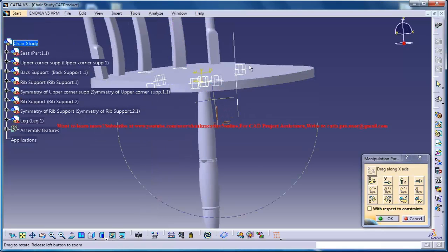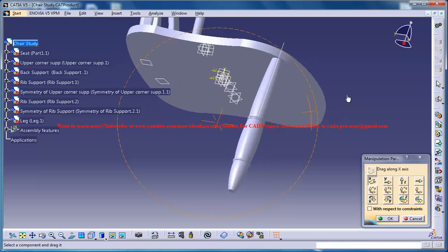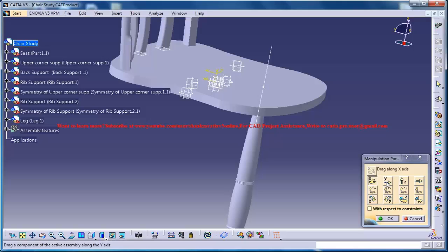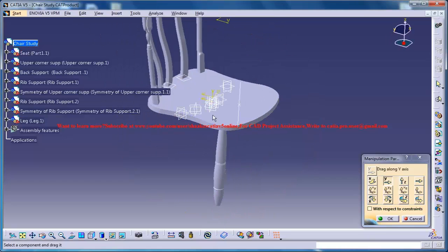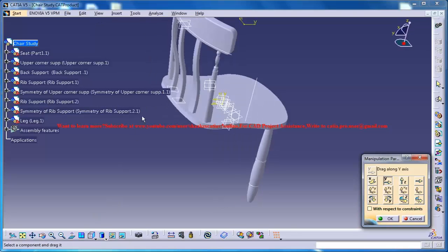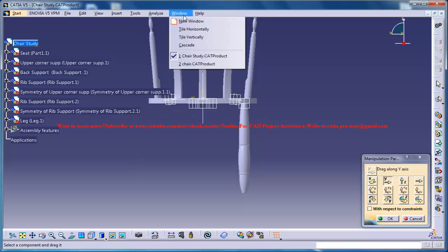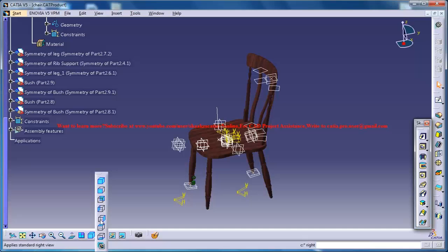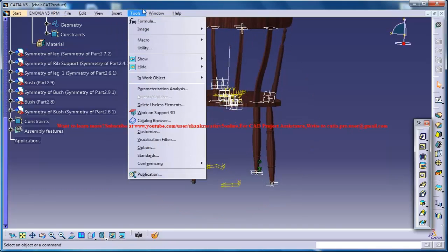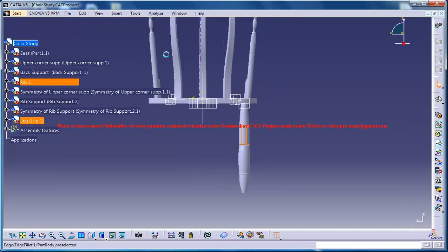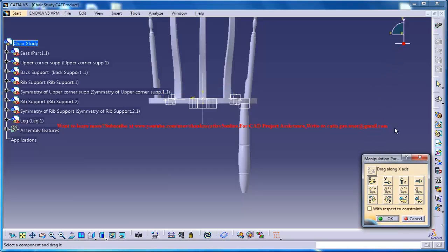Alright. Okay, this will be fine. Now what you can do is again come to the side view and just use this as your reference. Take the side view for this one. As you can see, there is a kind of slant. You could do the same thing here by selecting this and going for edit, move, manipulate. With respect to the y-axis, you could rotate it a little bit and bring this a little down. And again, click on OK.